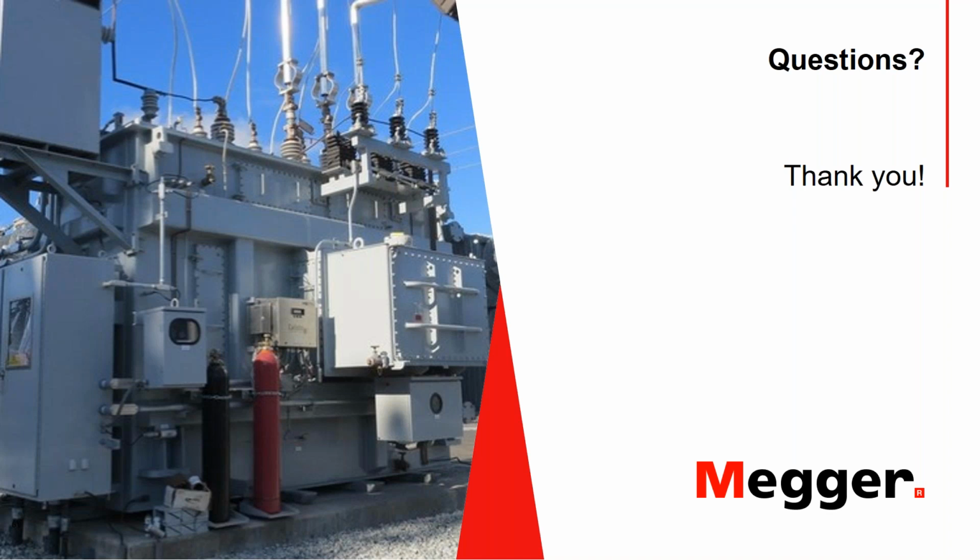Again, that question, I can easily tell the gentleman who asked that question has had experience in the field, and that is a true statement, because when you talk about OLTC, typically there is a reversing switch, or you might have a preventive autotransformer, and depending upon from which direction you are coming, your readings may differ slightly.